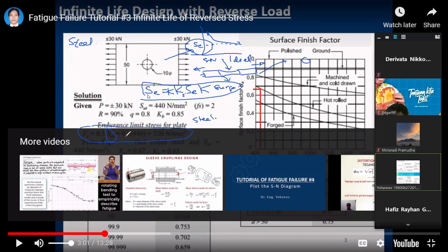If there is a correlation between the ultimate tensile and endurance stress, then we don't need to do the experiments, which are costly in time and other resources. We just need a single test, the tensile test only. Then we can predict the endurance. That's the main idea.